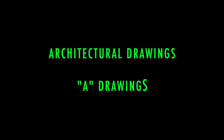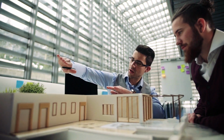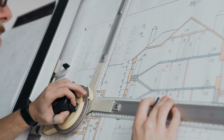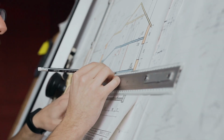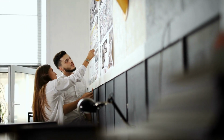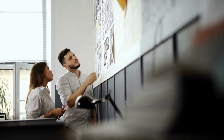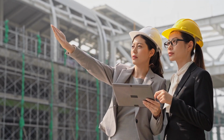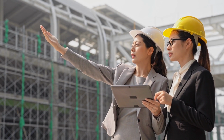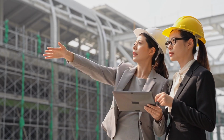The first type of drawing you should know about are architectural drawings. Architectural drawings depict the overall intent and appearance of a structure, along with expected dimensions, orientation, and details. These drawings are fairly detailed in terms of the amount of information that they provide, as well as the accuracy of that information. However, they are meant to depict the overall intent and are not necessarily specifically meant for construction. That being said, anything that's actually built is expected to fall within the parameters of what these drawings require, unless otherwise approved by the architect or client.